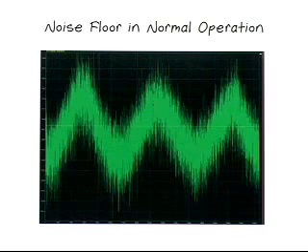If this were a narrowband application that happened to collide with the elevated regions of the noise floor, this represents a real loss of SNR on the order of 20 dB. While good layout can help reduce the effects of digital feedback, it may not be enough to eliminate the problem. The LTC2261 helps reduce digital feedback by providing a new proprietary mode to help mitigate it, called alternate bit polarity mode. Let's take a look at an example where digital feedback is likely to occur.